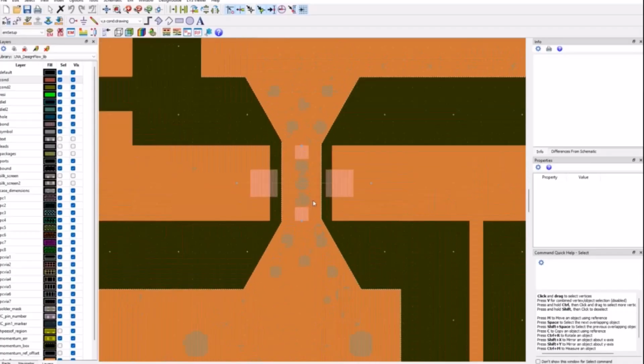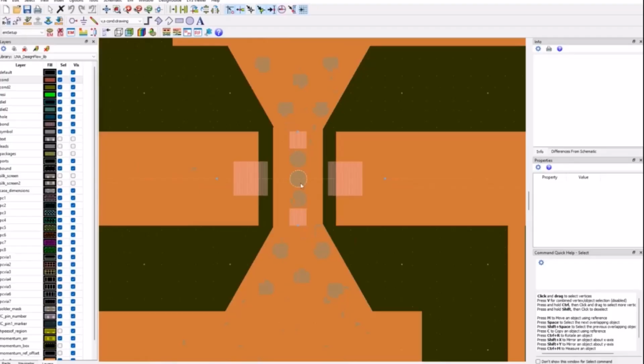Another good tip, if you're doing such design, consider the number of via holes I have, because this is where I will mount my design. And remember, I mentioned the source or the emitter terminal of your transistor should be almost fused with the ground. That is why you can see I have so many via holes where the body of the transistor will sit, and these via holes will provide very nice ground to the body.